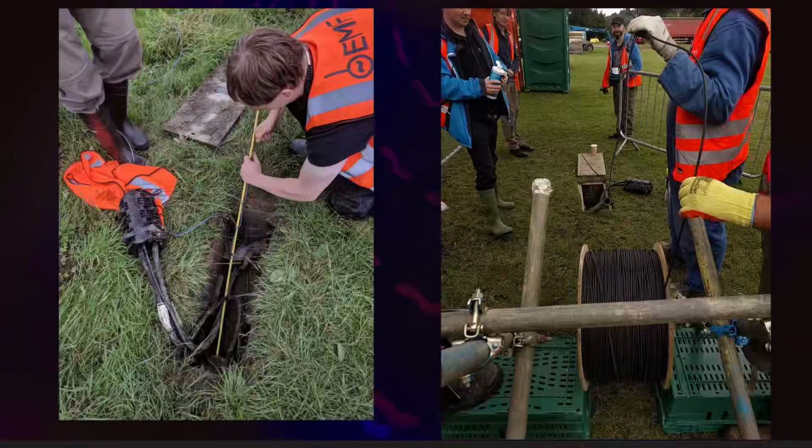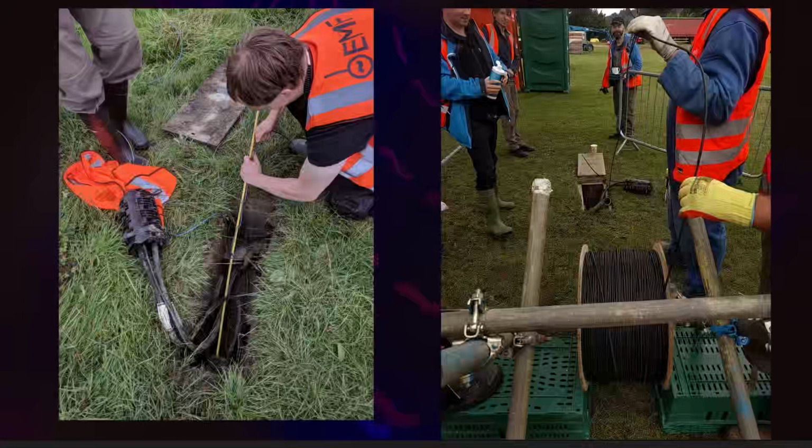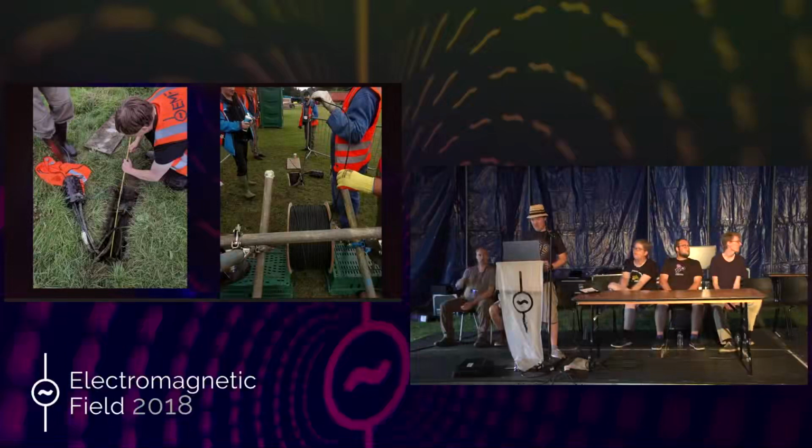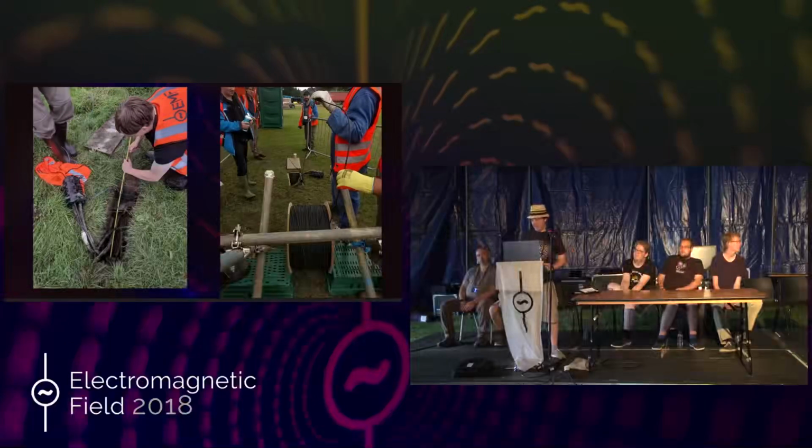So here we are. This is about 1.2 kilometers of fiber. We rodded last Sunday. Seems like a month ago. The manholes are every 100 to 150 meters, sometimes a bit shorter, but for each one we push this yellow, very stiff rod through, pull back a rope, and then pull the rope back through again, all the way.